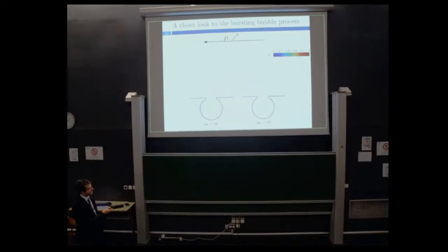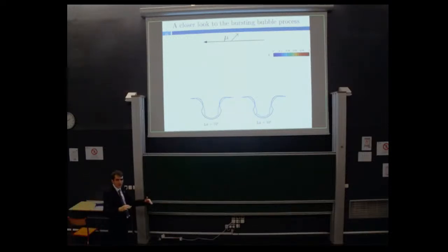So we start here with the initial collapse, and we observe the different time steps. And here what we can see, on a very high Laplace number, so very low viscosity, we are observing the propagation of a lot of capillary waves inside the bubble cavity. If we increase the viscosity, we observe here on a Laplace of 1000 that there are almost no capillary waves. There is in fact only one capillary wave. So the viscosity is damping the amplitude of the capillary waves, which explains why we've got here only one main capillary wave.